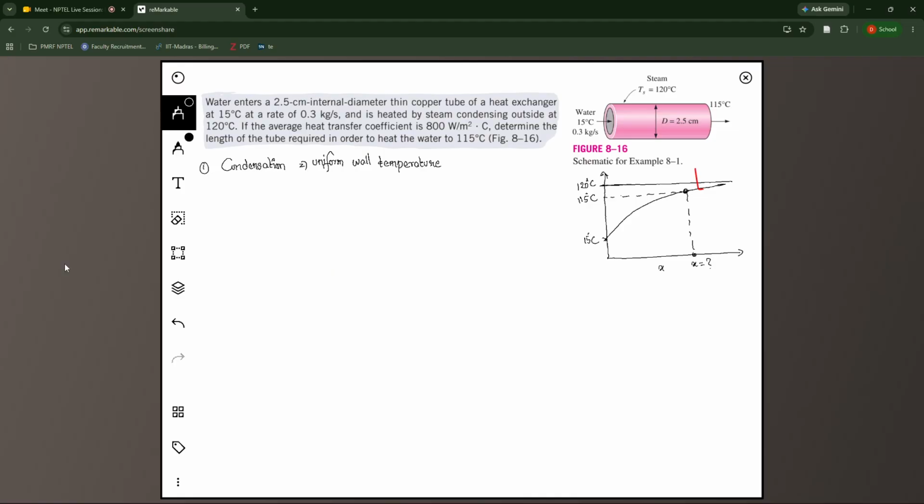Beyond a point, every meter of copper tube that you use will add cost to you, so beyond a particular point the benefit you get is reduced. For example, if you make X amount of money by condensing some amount of steam, then as you increase meter by meter, the cost also increases, but the profit you get by condensing steam is reduced. So there is a limit where you have to stop.